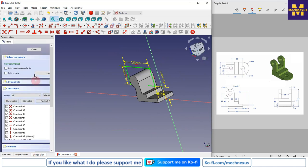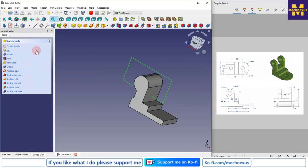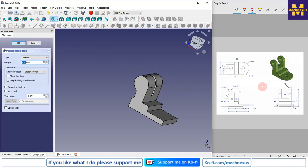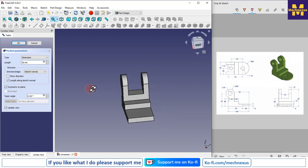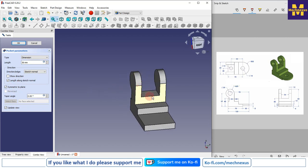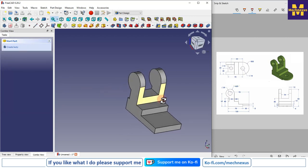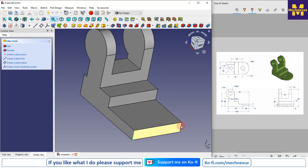Now we will come out of the sketch and go with a cut, and the cut is 36, so I will give 36 and click on symmetric to the plane. You can see that at the middle portion material has been removed. Now if you see from the top view, there is an R30, so I will select this edge and this edge and go with a fillet